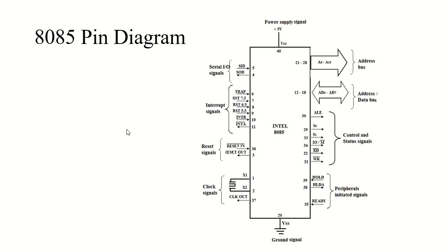and the flag register is connected to my arithmetic logical unit, ALU, and when the operation is performed by ALU, the result is transferred to the internal data bus, and the status of the result will be stored in the flip flop. Now there are five different flags.